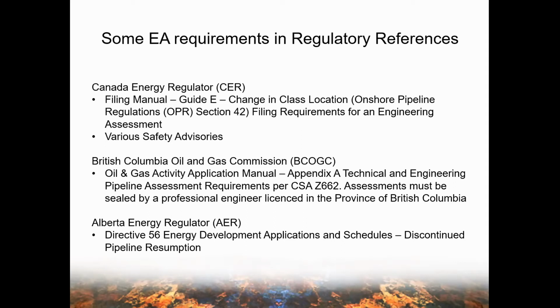And if you note in various safety advisories that the CER has, they do point to the need for an engineering assessment. An example from BCOGC, or the British Columbia Oil and Gas Commission, is in their Oil and Gas Activity Application Manual, Appendix A, where they point directly to the requirements of CSA Z662, and they do note that assessments must be sealed by a professional engineer licensed in the province of British Columbia.